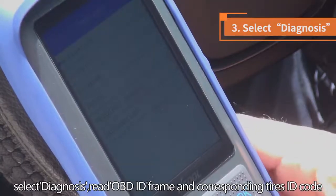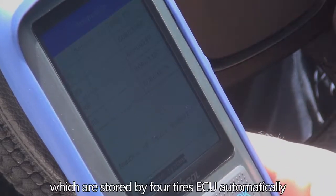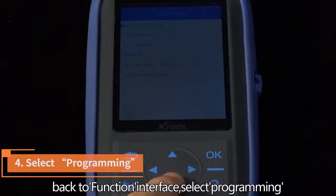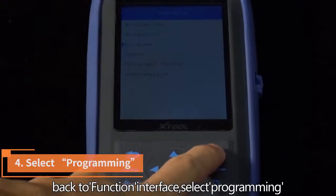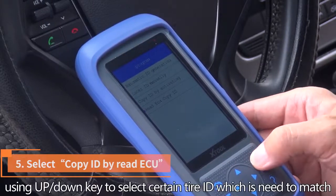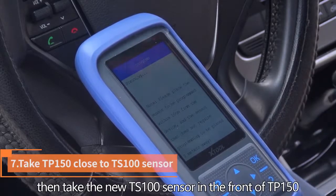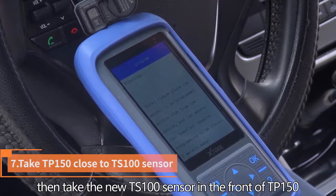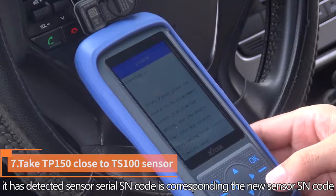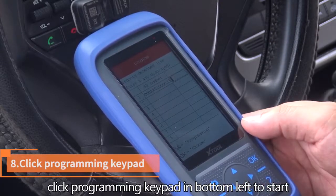Select Diagnosis, read OBD ID frame and corresponding tires ID code which are stored by 4 tires ECU automatically. Back to function interface, select Programming, select Copy ID by read ECU. Using up-down key to select certain tire ID which is needed to match. Then take the new TS100 sensor in front of TP150. It has detected sensor serial SN code is corresponding to the new sensor SN code. Click Programming keypad in bottom left to start.